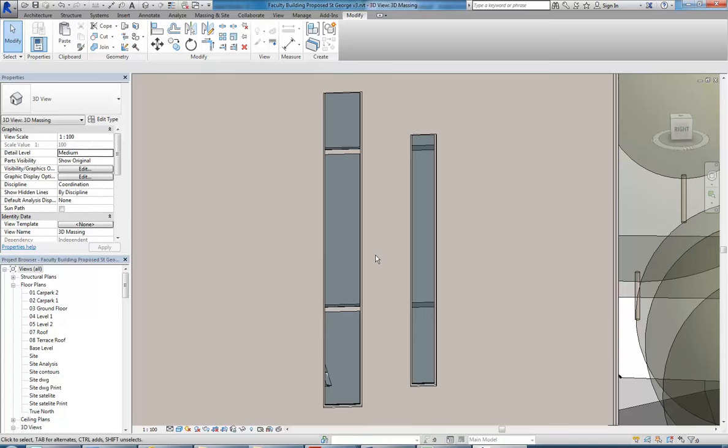So there's a property you can just go in and change the degrees, and that way when you're doing your rendering, you can get different amounts of sunlight in through your louvers just by changing that property, and you can get hundreds of louvers to change angle in one hit instead of going and doing that manually, which is obviously a huge amount of work. So yeah, just think about the things you could do just by changing some properties, and maybe have a go at making some of the families you need.